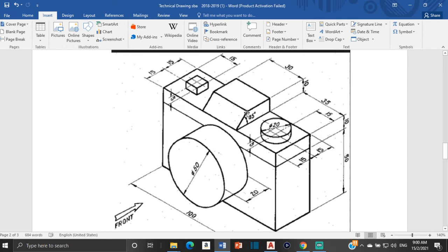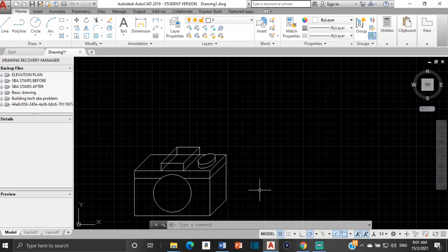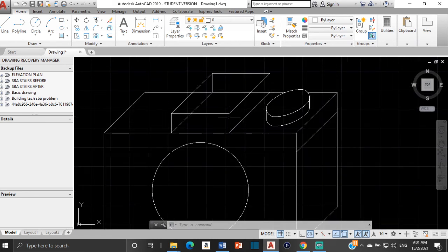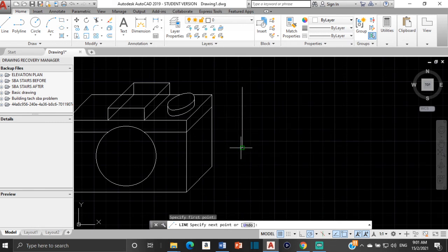All right, why 60 degrees? Because this line is 30, and if there's a 90-degree angle here, in order to properly bisect that angle, we'd have to draw that line at 60, because 90 minus 60 is 30, and 60 minus 30 is 30. So in the case of our oblique projection, that line is 45. This line here is 45 and this line here is 90. If we're to draw a line that should properly bisect this, as you know, a 45-degree angle would properly bisect a 90-degree angle if it was done in two dimensions, perfectly like that.